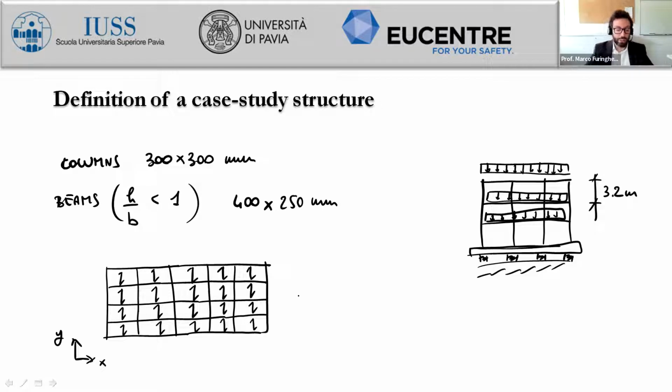If I just look at this region, we will consider the following definition of external loads. We will have 40% of the total resultant load for this portion of the floor going to the X spans, whereas we will have just 10% for all the Y spans.